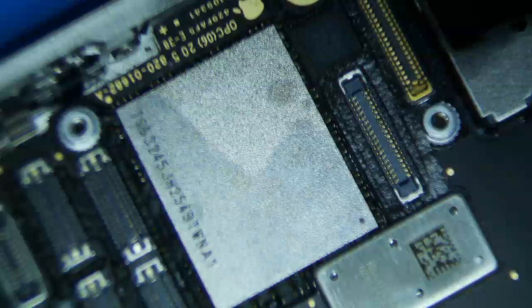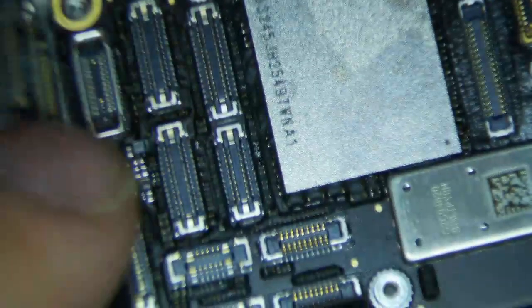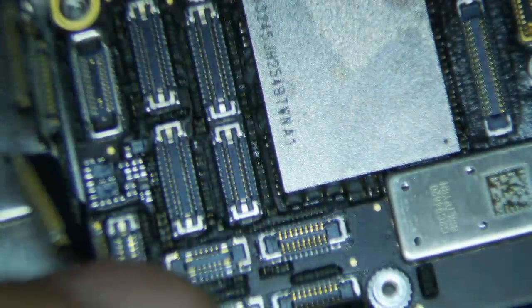What's up? I have an iPhone 11 Pro here that has no power. Nothing on the display. Plug it in, and I get 0.6 amps on the USB ammeter. I plug it into my DC power supply, and I also get 0.7, 0.6 amps. Immediate draw. All right.